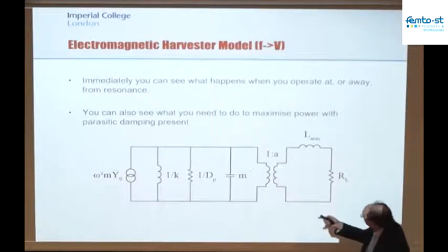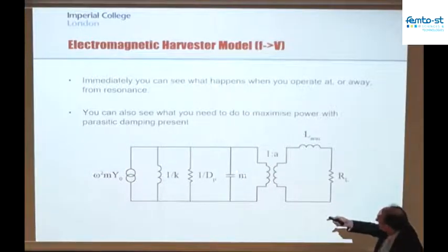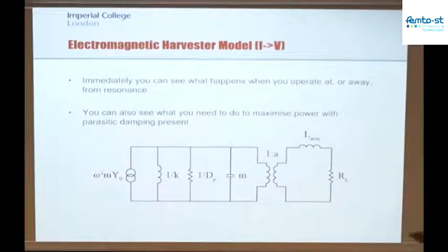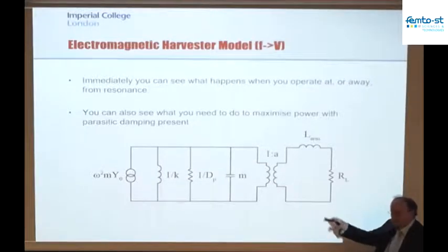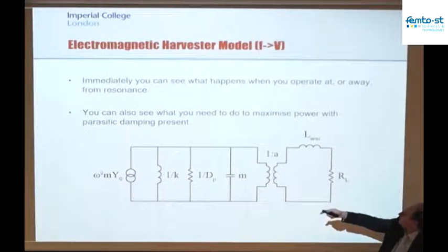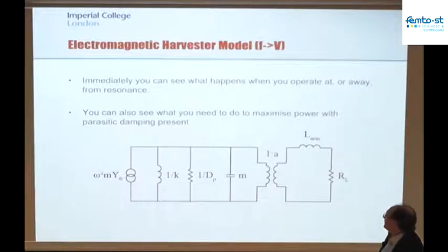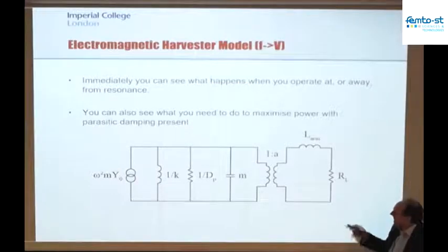And then we have to be able to map the behavior of the mechanical domain into the electrical domain, and we do that typically through the transduction mechanism, of course, and the transduction mechanism needs to have some turns ratio on it, like a transformer, in order to map, in this case, the velocity, for instance, which is voltage across these components, into generating a current or a voltage in the electrical domain. And depending on whether we use an electrostatic transducer or a piezo or electromagnetic, that will change the turns ratio present on this transformer here.